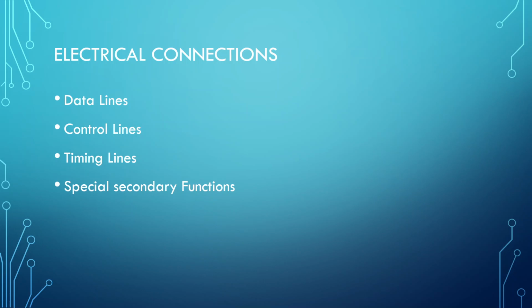And the control lines, as far as I'm concerned, when things start being a bit more complicated. Oftentimes, if you get into the world of TTL serial, all you do is ground, transmit, receive. 3 wires, you're done. All you need to know is there's data coming in, I need to be able to send data out, and I need that ground, that 0 ground rail, whatever you want to call it, to have a complete loop. As long as I've got those 3 lines, I can talk to other devices. In the world of serial, it's not quite that simple for RS232.